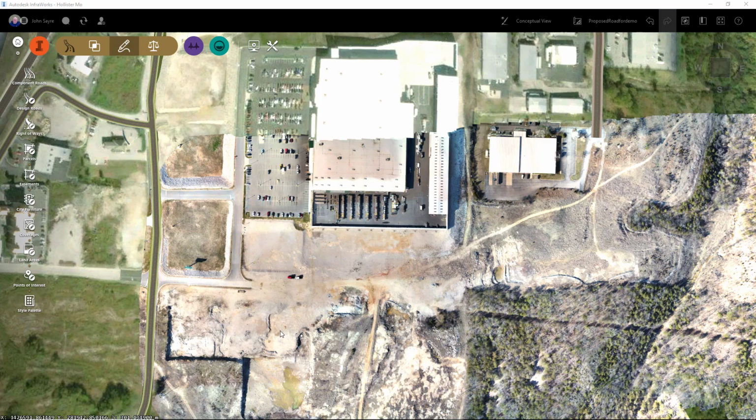So what we're going to do is generate a component road, and then we're going to bring that component road into Civil 3D 2019, and at import, with the new functionality of being able to generate a corridor from a component road, we're going to be able to see a corridor that has been automatically generated at import using simple subassemblies and assemblies. We can then take and add our custom subassemblies to either the existing assemblies, or we could actually change out the assemblies totally and update our corridor from that.